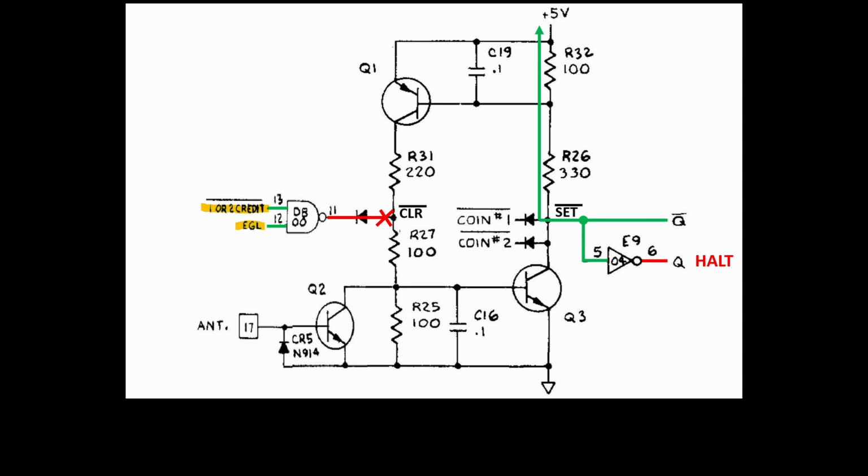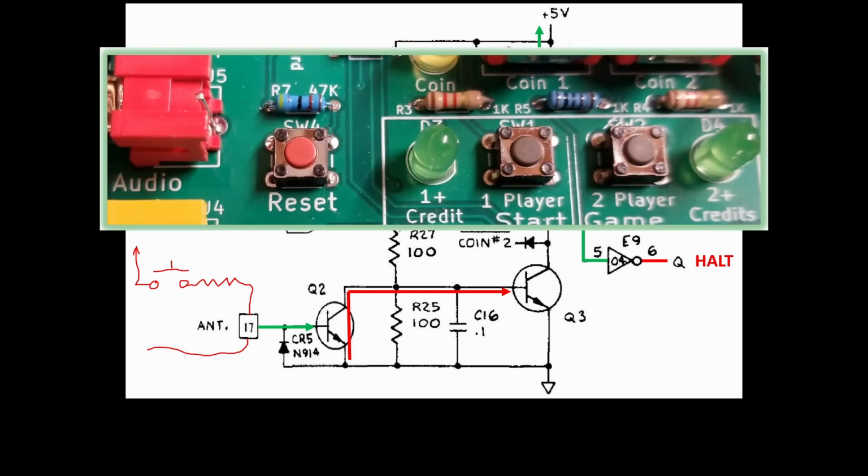The last way to reset the latch is when a static discharge is detected by a short wire connected to pin 17. This turns on Q2, dropping the base of Q3, turning it off. This logic prevents abnormal operation after a natural static discharge and keeps unscrupulous players from trying to shock up credits. We can simulate a discharge with a light pull-up on the base of Q2, and we included this exact setup on our control board for purposeful resets.